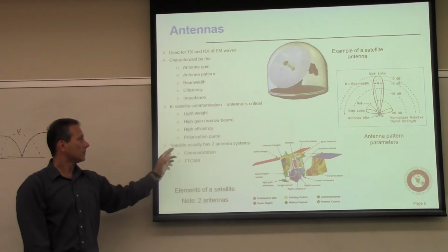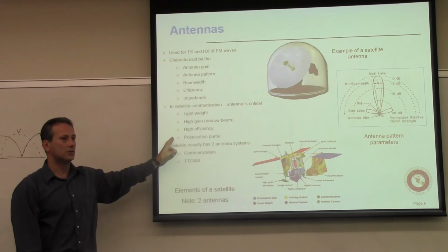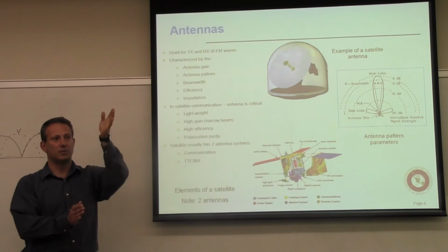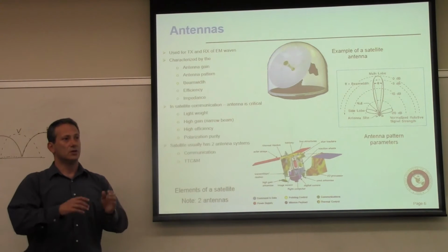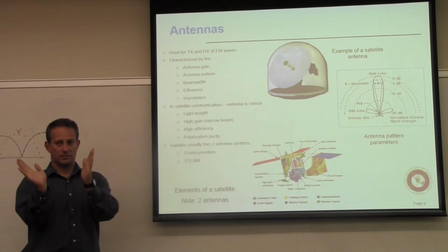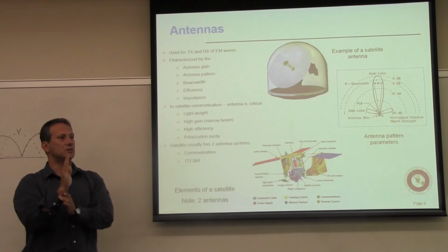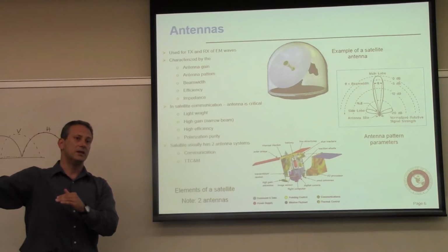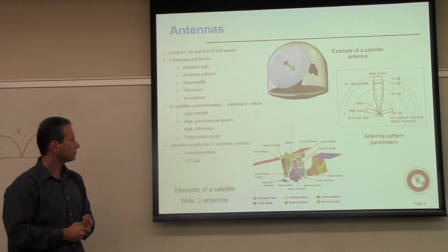This is not any sort of luxury. It is a necessity, because remember, we reuse polarization. So if you're operating on channel 1 and you're horizontally polarized, you want whatever you radiate in the vertical direction to be as minimal as possible, because that directly impacts somebody else's ability to reuse it on channel 2.